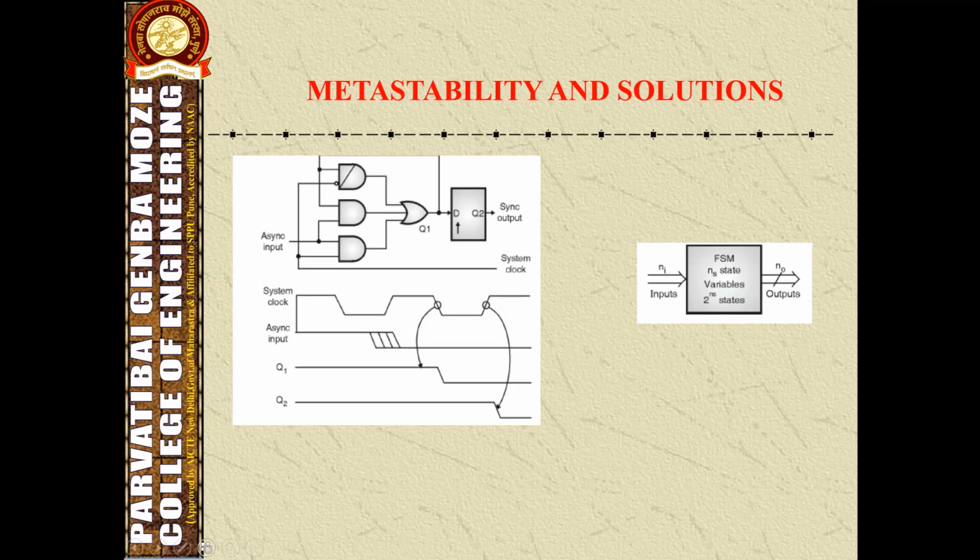Here the figure shows the gated latch, which internally latches the asynchronous input on the falling edge of the system clock and generates the signal Q1. The input for Q1 through the internal feedback path eliminates possible hazard conditions during the clock's high to low transition.